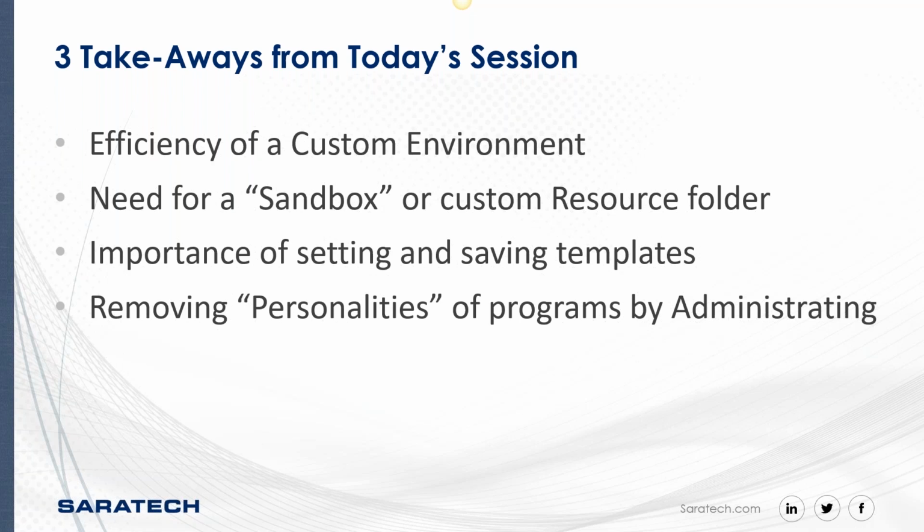The importance of setting and saving templates: if you do it incorrectly, then you're going to have to do it continually each and every time. If you do it with the correct methodology, then those templates will be rolled out like new features. And removing personalities from programs by administrating: there's a very large amount of information out there on why to take personalities away from programs. The person on the floor running the part should never be able to tell who programmed it. When that happens, then you know that you are as efficient as possible.